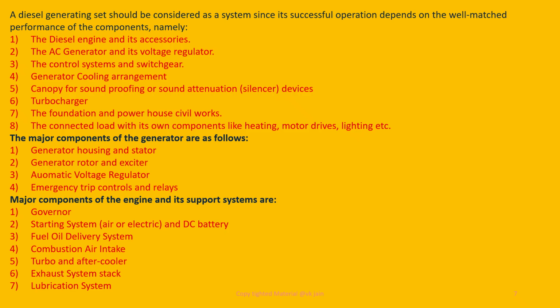A diesel generating set should be considered as a system, whose successful operation depends on well-matched performance of components, namely the diesel engine and its accessories, AC generator and its voltage regulator, the control system and switchgears, generator cooling arrangement, canopy for soundproofing or sound attenuation, that is silencer.